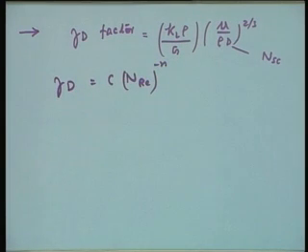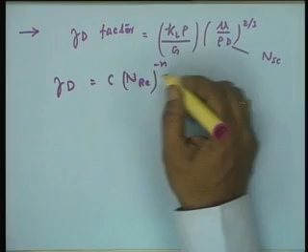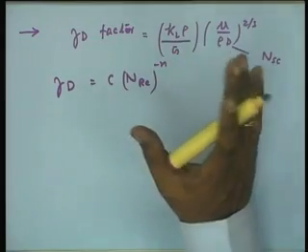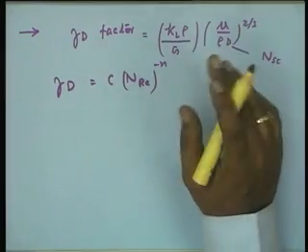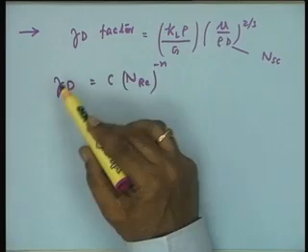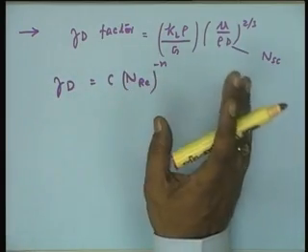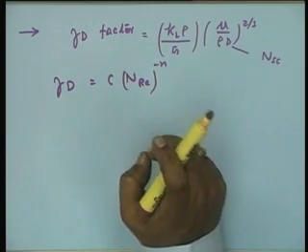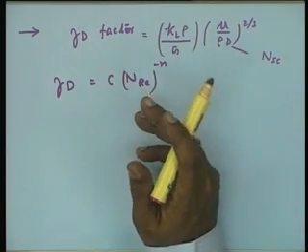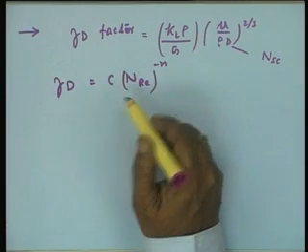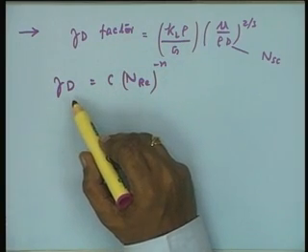Now, of course, a very general relationship for JD factor has been given, that it is a function of Reynolds number to the power minus n, and of course, under different conditions of particle shape and in the range of Reynolds number, the magnitude of C and n varies, and that can be estimated for a particular system. And of course, a large number of correlations giving the values of C and n have been proposed under different conditions, and one of them which meets the actual reaction conditions can be chosen from the literature and used for estimation of JD. Okay.